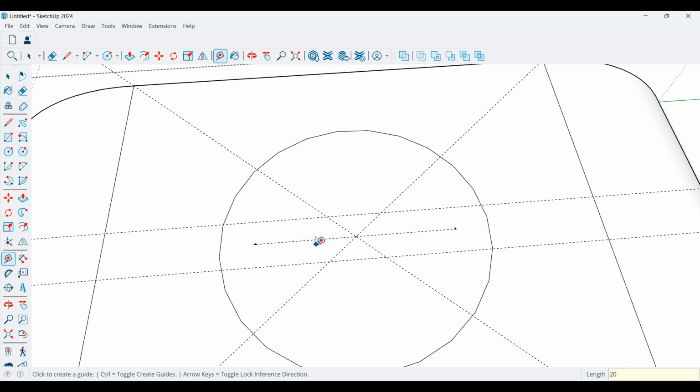Now to make the arc, we need to give it a center point. So we need to come back. The width of this is 10. So we need to come back 5, which is half of 10. Guide point gets placed, 5. And then get our arc tool, which is that one. Click on the guide point, click across to the edge, and then drag the half circle around. Do the same on here, on the guide point, drag it around until you get a half circle.